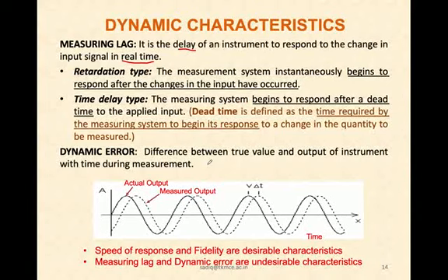It can be different. That means even if there is a force happening at a particular moment, the output given may be a little away from the actual instant. So the difference between the true value and the output that is shown is called a dynamic error, the error between the actual value and the true value again, but in the